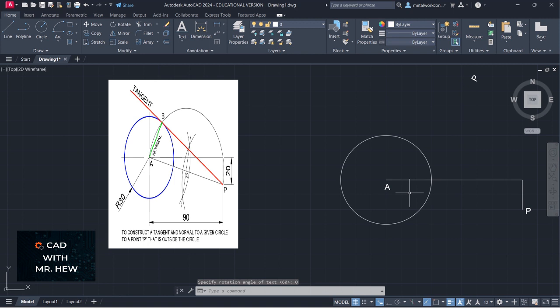So you learned something today, right? The command stores the previous values that you used before. So if I used a height of 3 millimeters the previous time I used the single text command, it's going to bring 3 into it as an accepted default. So you have to change it to what you want if you want to change it.